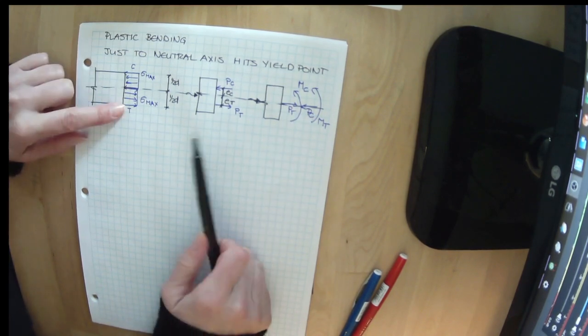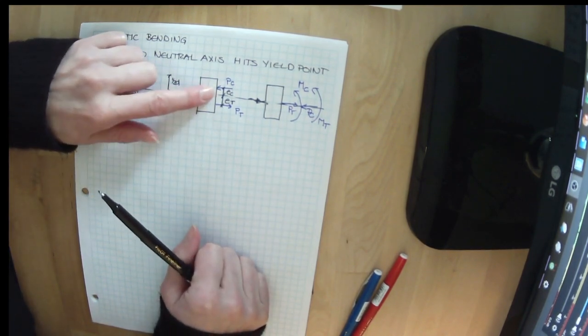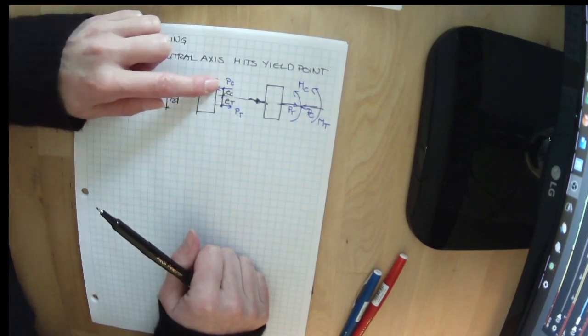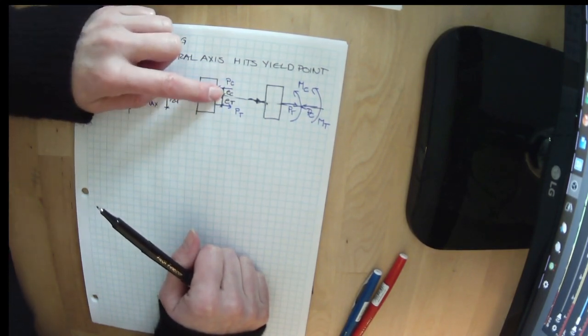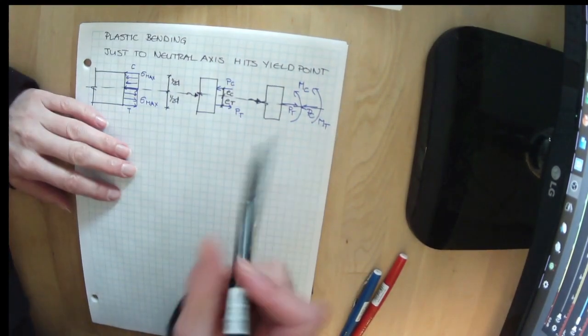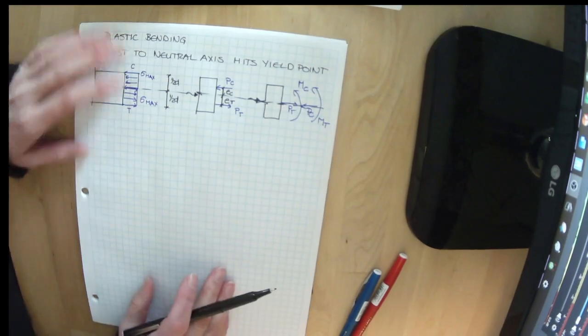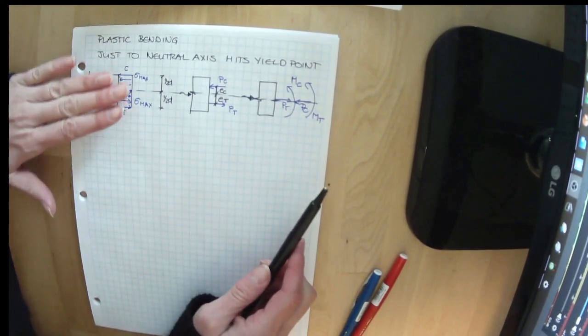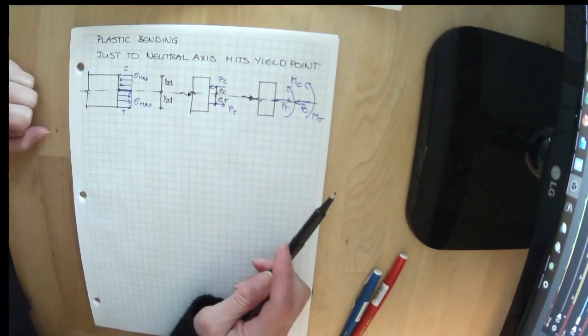So this is the equivalent to this. We've just taken the stress profile, redrawn it as analogous point loads and its eccentricity, and then we know that a point load with an eccentricity can be redrawn as a moment and a point load through the centroid, or in our case along the line of the neutral axes. So we've just drawn the same thing 3 different ways.